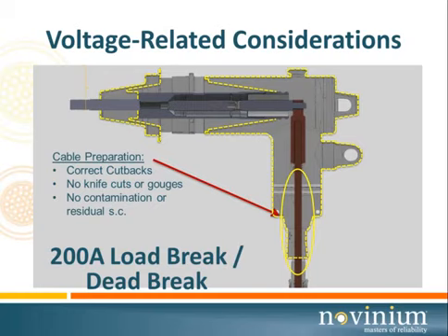The next thing we have to do is make sure we have no contamination. The contamination on the insulation surface usually comes as a result of residual pieces of semicon, microscopic, very small, actual carbon particles that are embedded on the surface of the insulation. How do we remove those? Some utilities allow their splicers to go in there with fine sandpaper and remove the contamination that way. The better way is to use a solvent, soak a rag with solvent.